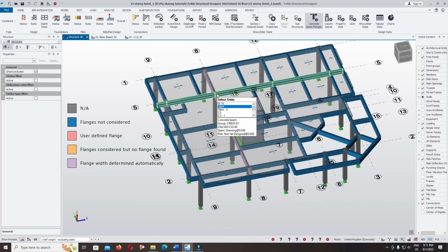The program automatically validates the slab as a potential candidate for being a beam flange using a number of criteria. The slab can be on one or both sides. One side can be an L beam and both sides can be a T beam. The slab must be a reinforced concrete slab. If there are slabs on both sides of the beam, they may be of different depth and the depths may vary along the length of the beam. The slab must have a top surface consistent with the top surface of the beam. There must be a slab overlap greater than 50 mm or 2 inches, as shown in the following illustrations.